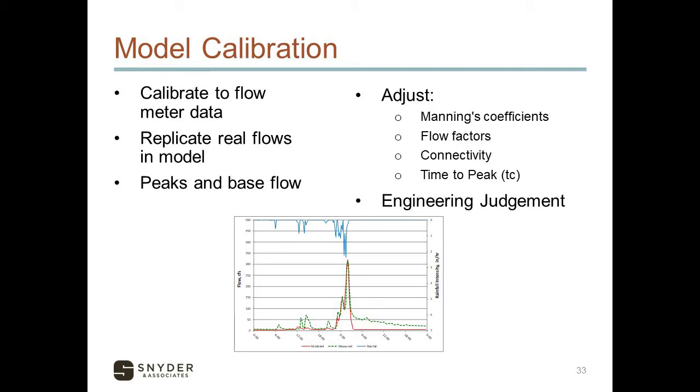So taking the model, doing a capacity evaluation, whether that's just for a singular pipe or a small part of the system, or doing a system-wide capacity evaluation. We're looking at hydraulic grade lines to identify certain restriction points. And then as we look at prioritization, working downstream to upstream. If we start upsizing upstream before downstream, we're going to be sending more flow to already restricted systems. So just making that point to prioritize as you work your way up.